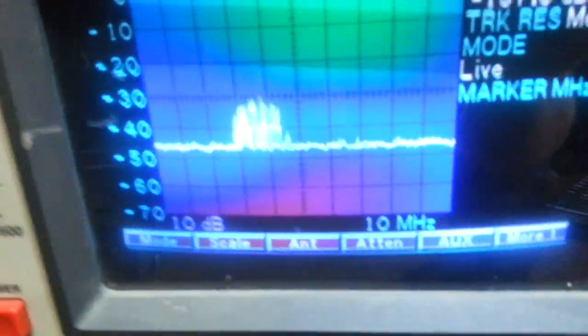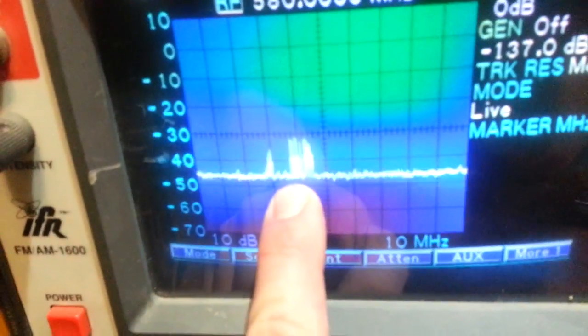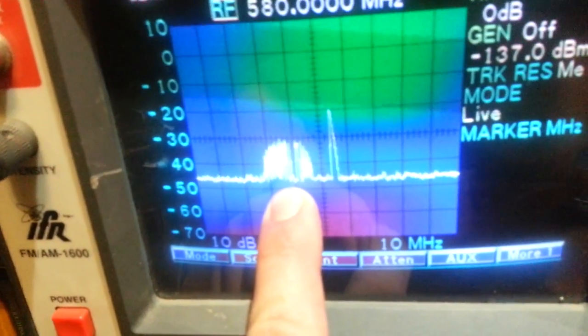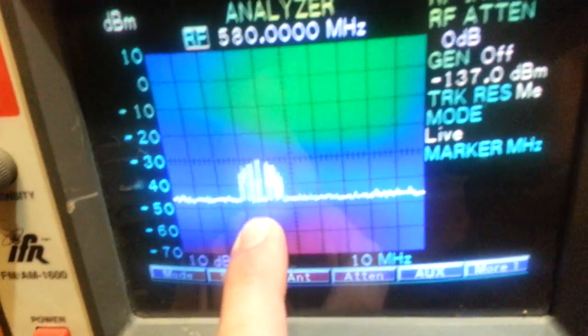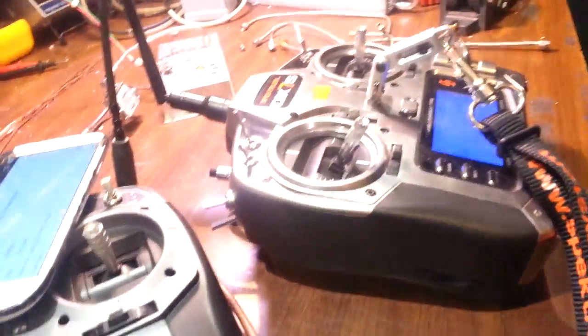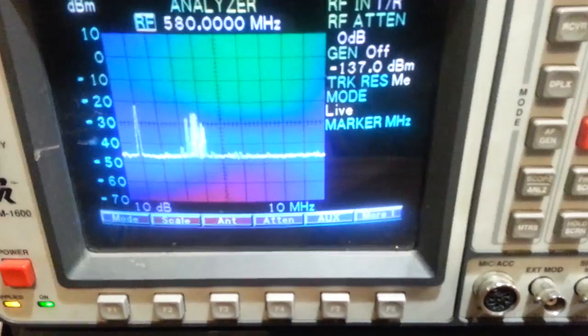They each got their cool little names and stuff like that, and they do all their technologies to mitigate this. But if you are flying in the city, or anywhere near anybody who has that thing on the wall, a 2.4 gigahertz wireless access point, there is going to be lots of that. That signal right there is the Wi-Fi signal from the phone. It's not nearly as powerful as that thing is, but your receiver picks up all of that.